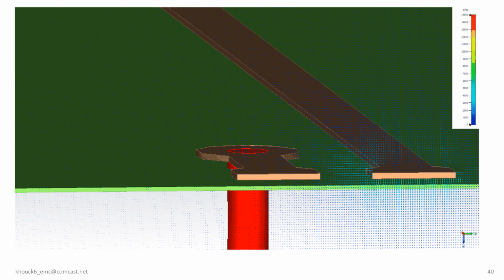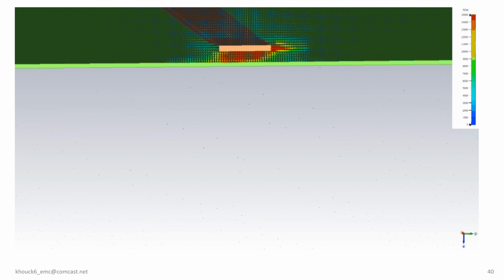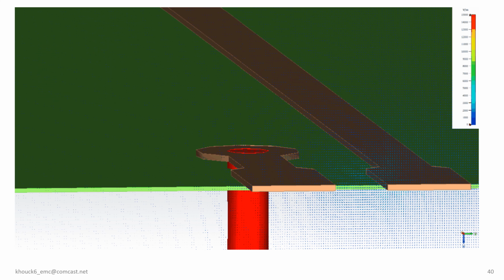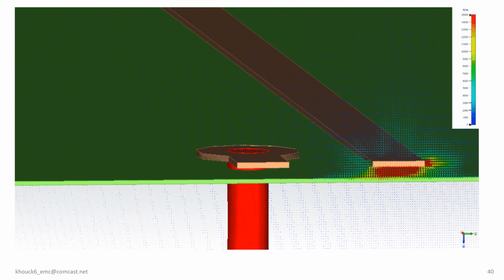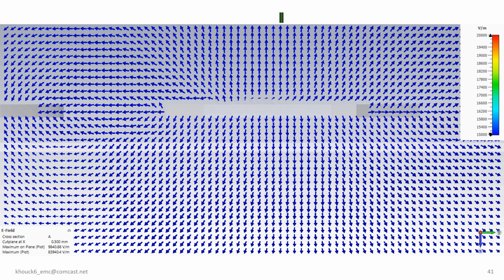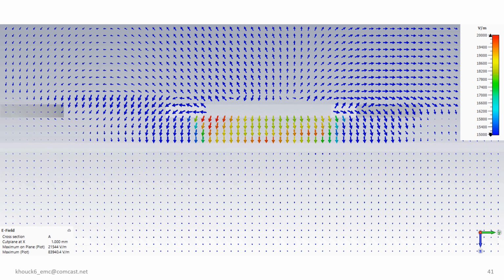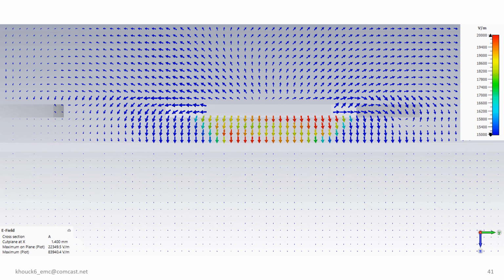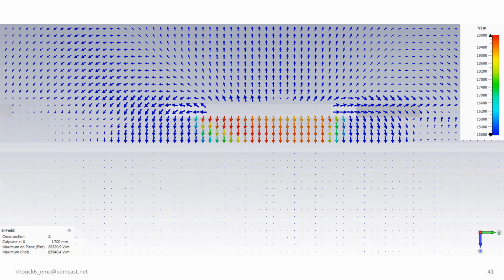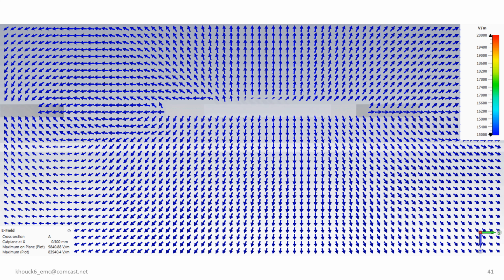A fly-through of the cross-section along the propagation path will show the relationship between conductors separated by an insulator. The animation illustrates a notable disparity in the relationship strength between the part pads and along the trace. This variance in relationship strength induces a deflection in the transition time of the signal.